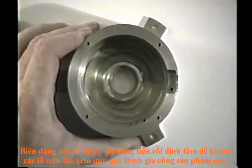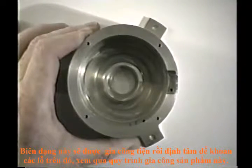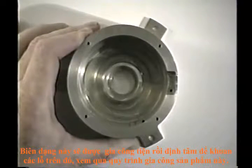Take a look at a part like this. Now, there is no square corner on this part. So what we normally do, this part would be partially turned in a lathe, and we have to indicate the center of this part, and all of our dimensions would come from the middle of this part. So we would be forced to be using plus and minus dimensions. And let's take a look at this and make up a little sequence of positions for this type of part.